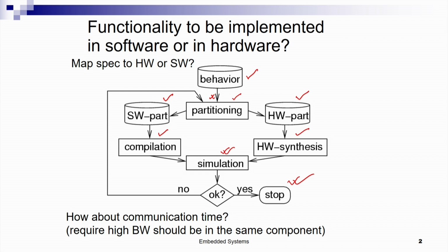Essentially, we do a design space exploration into various types of partitions. A component can first be tried in software, then in hardware, with different components having different cost variations. We will take another hardware software partition, again implement, again compile it, again do a hardware synthesis, maybe a high level synthesis to get an estimation of what will be the hardware cost, area, etc.